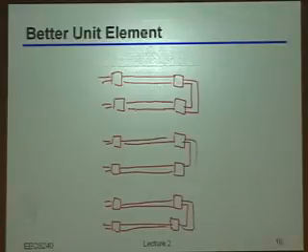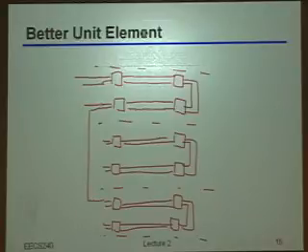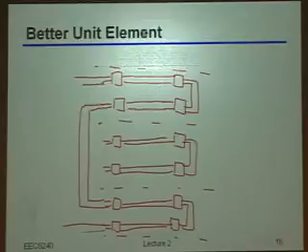Okay, right? So remember, each one of these things is an individual unit element. To construct an array, or rather, let's say one resistor with value R and another resistor with value 2R, the way you do that would be something like the following. You take that upper element, you connect it in series with that bottom element, and that would come out from there.